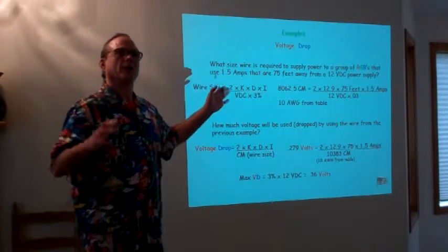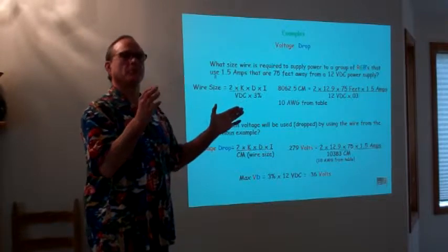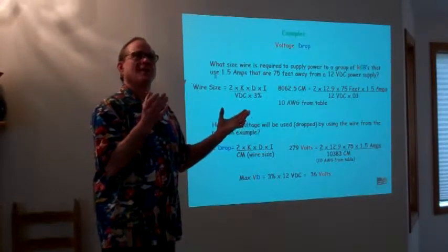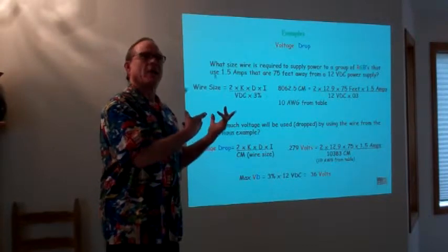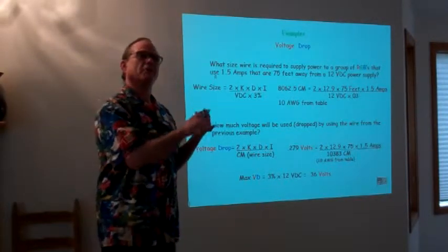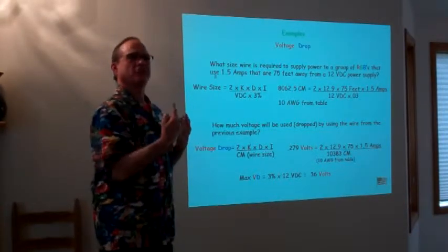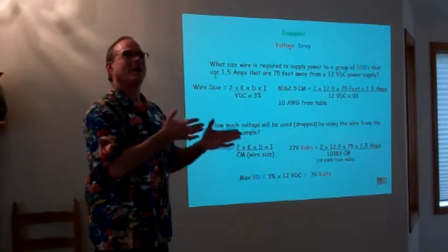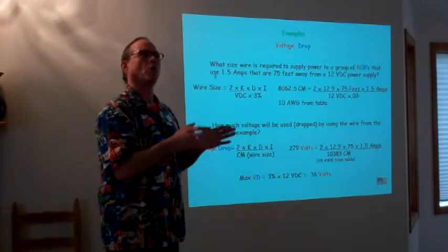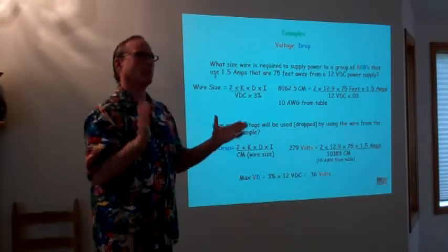What we're doing is we're actually getting the power to that string. Now, as you mentioned, the string comes from the factory already figured at a specific wire size. That wire size is calculated by their engineering staff, based on the voltage that's going to be in that string and the actual resistance of that string. If they've done their homework right, they have sized that wire to handle that ampacity for that string. So we don't have to worry with that.